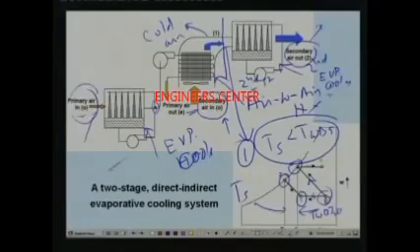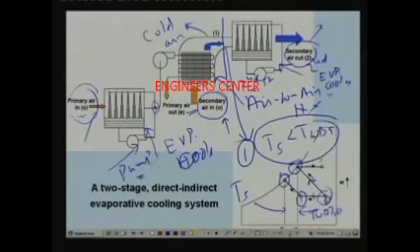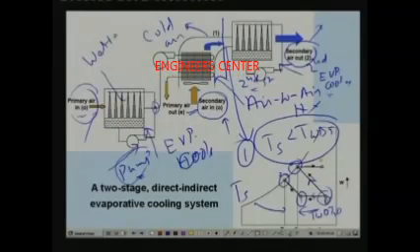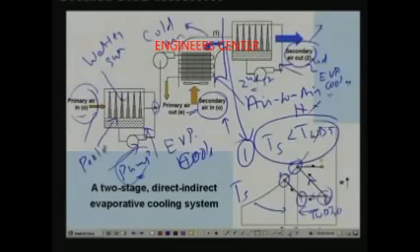One thing I forgot to mention is the use of this pump. We have to use a water pump in an evaporative cooler because in a typical evaporative cooler you have to maintain these wetted surfaces continuously wet. These are the wetted surfaces which have to remain wet continuously. So, what you have here is a pool of water. This pool of water, the pump is connected to this pool of water.